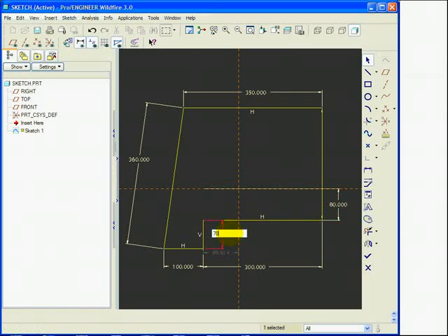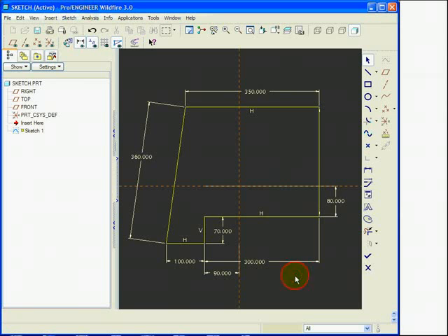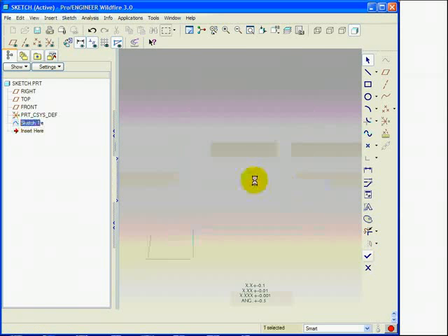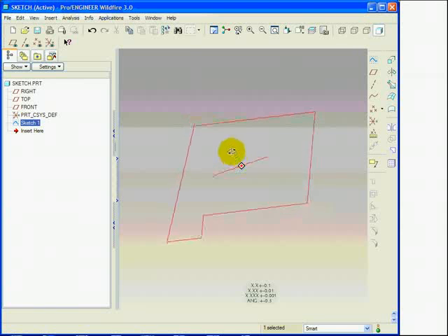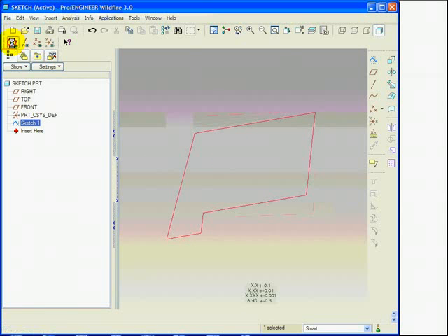The difference between a strong and a weak dimension is the following. Weak dimensions are what the program suggests as a dimensioning pattern for the section, whereas yellow dimensions have been either modified, inserted, or strengthened by right-clicking strong. I quit sketch creation, tick here.